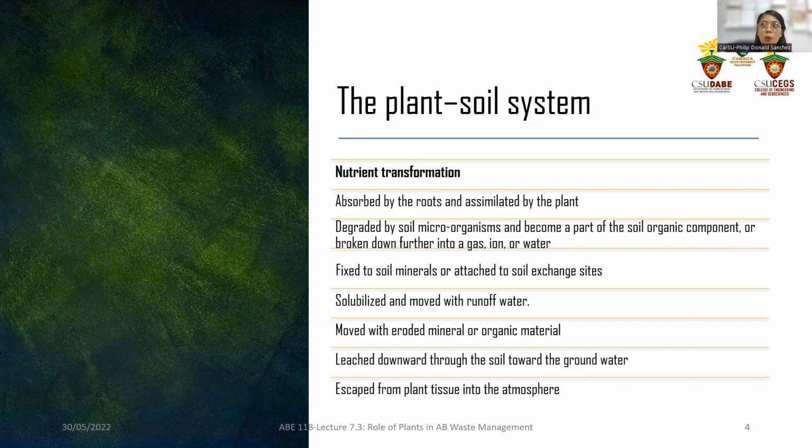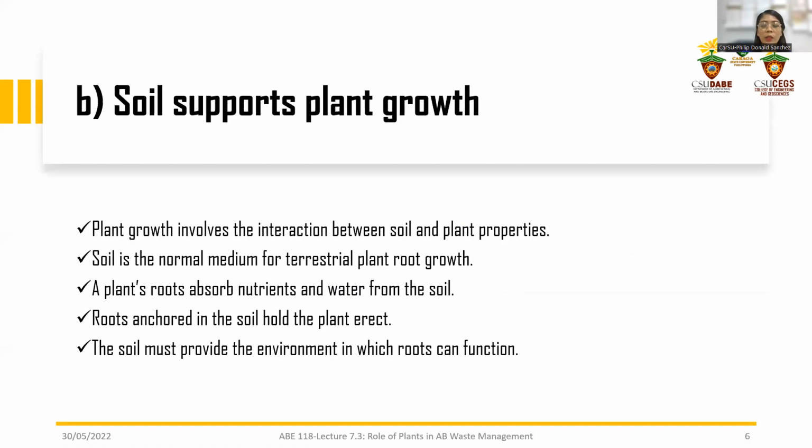So plants act as a catalyst or provide a better environment to promote the transformation processes and also the growing of plants. It moderates soil temperature, reduces evaporation from the soil surface, and also provides an energy source in carbohydrates and aggregates soil particles which promote high soil aeration. And as I mentioned, it provides a better climate for a wide variety of soil microorganisms.